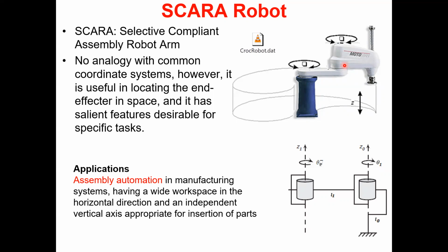That difficulty is there in machines as well. If a machine has a rotary joint and it has to maintain an arm connected to the rotary part of the actuator horizontally, it has to produce additional torque to keep it in that position, compared with when the arm is in the lower position or vertically upward upright position.